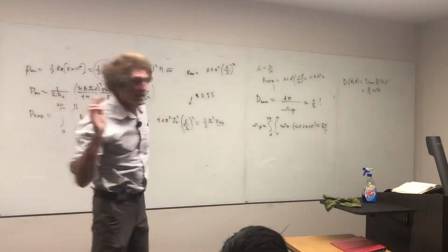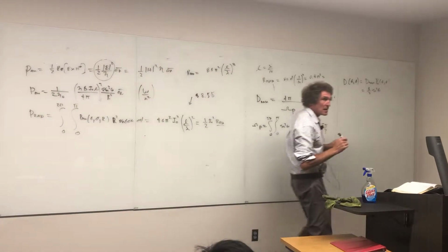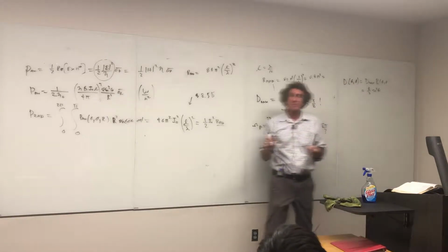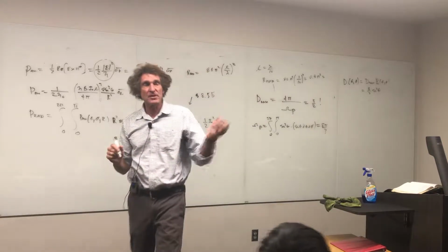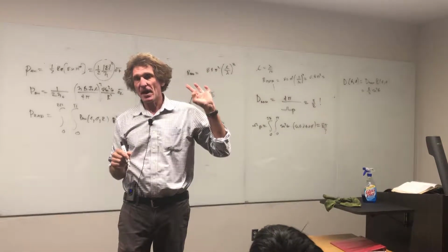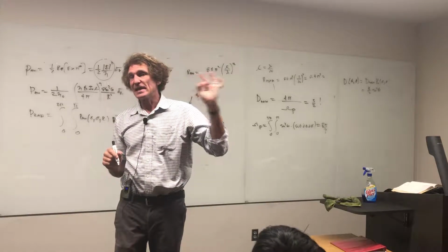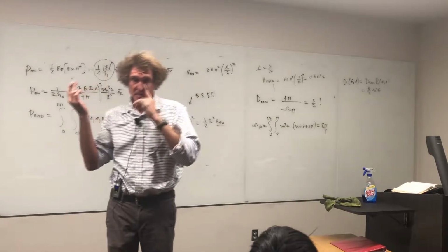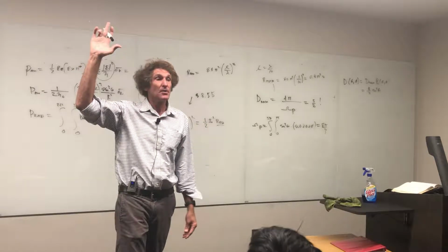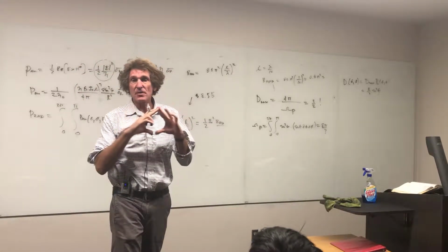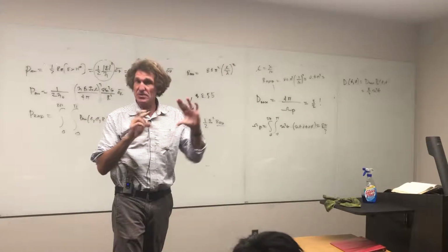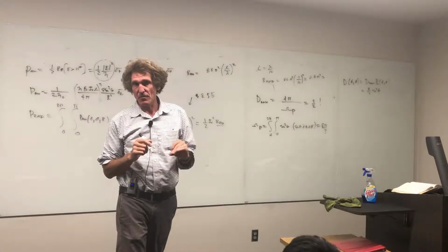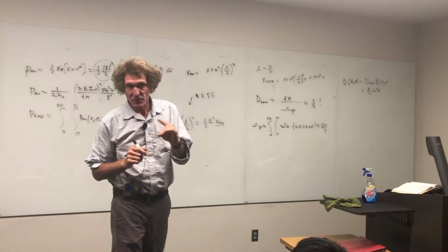All right, now, hear me. That right there is almost what we really want, but what we really want was the gain, and that depends on the dissipative resistance, all right? Which means you also have to know the frequency of operation, because remember, the higher the frequency of operation, the more the current clings to the surface, right? And the higher your resistance. Do you all remember that? That would be the loss resistance. I want to make sure I'm talking to the right crowd. You remember what we talked about, R AC, or high frequency, where it's much higher than just the DC resistance of the wire because the surface only has the area of one skin depth to run through, right? Everybody with me on that? That's what you'd use for the dissipation.